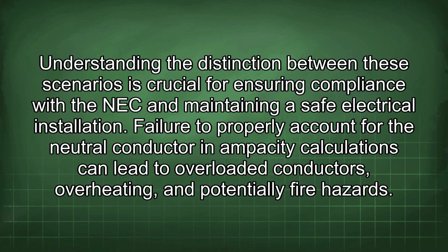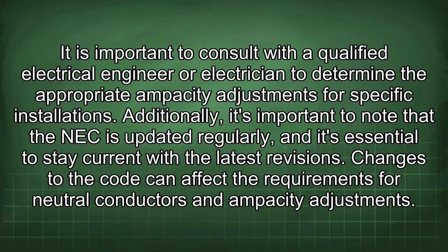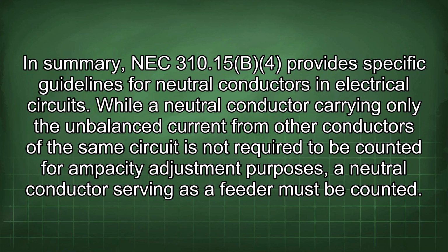Failure to properly account for the neutral conductor in ampacity calculations can lead to overloaded conductors, overheating, and potentially fire hazards. It is important to consult with a qualified electrical engineer or electrician to determine the appropriate ampacity adjustments for specific installations. Additionally, the NEC is updated regularly and it's essential to stay current with the latest revisions. Changes to the code can affect the requirements for neutral conductors and ampacity adjustments. In summary, NEC 310.15(B)(4) provides specific guidelines for neutral conductors in electrical circuits.